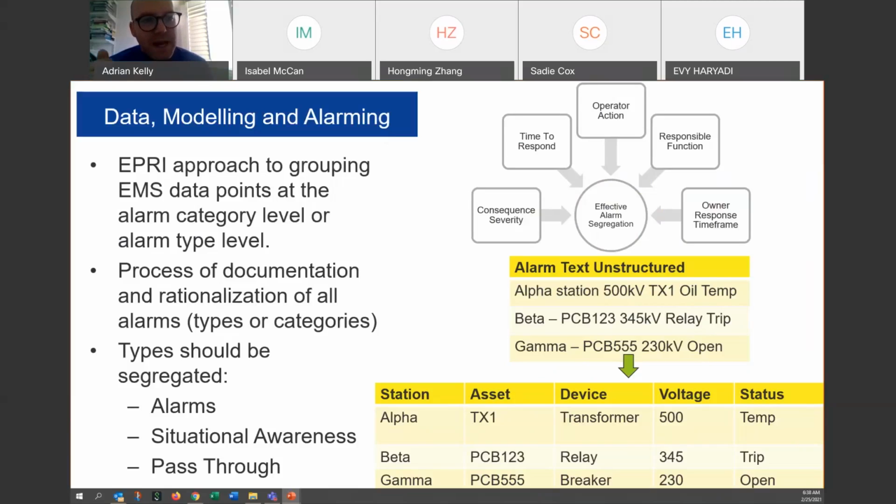I'm not certain about your processes, but in 95% of utilities around the world, the alarm system is not very well designed or not very functional. There are text issues, alarms aren't prioritized correctly, and there are alarm floods for events instead of concise information on the system.